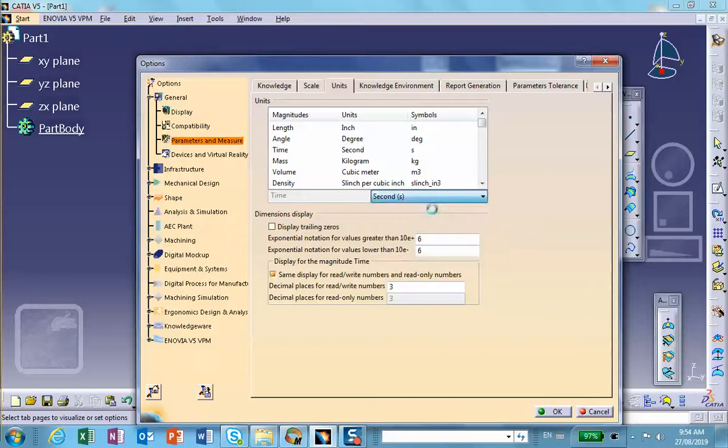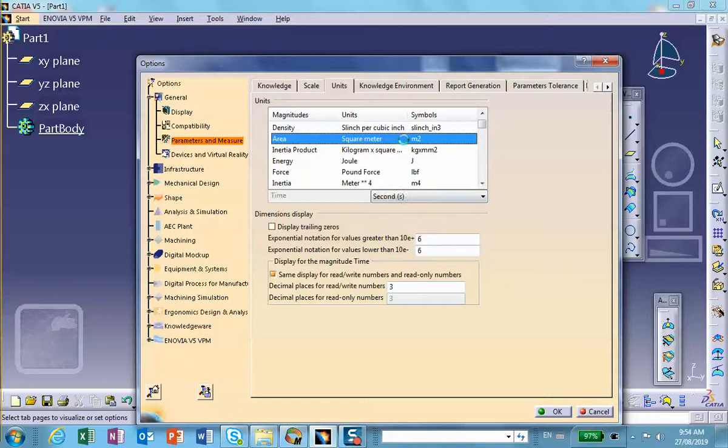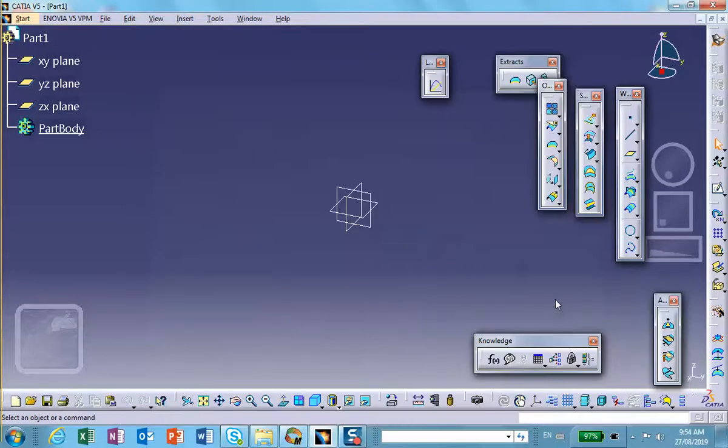Okay, we don't have a distribute lump mass here. Density is set as pound per inch cube. Force is pound, and I think that's okay, area inch squared. How about that? Although it's not necessary to do this, you can input any unit that you want. It's going to get converted. So yeah, that's good. All right, we're going to use beam elements.